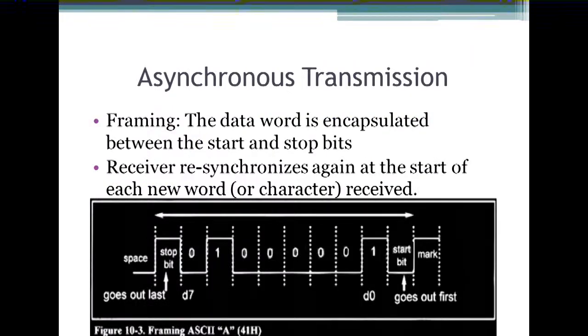Looking into UART, which is asynchronous: in asynchronous transmission, characters are transmitted one after the other, and they undergo framing, in which each character is added with some external bits, the start bit and the stop bits, which indicate the start and stop of characters, helping to synchronize the transmitter and receiver. After transmission of the start bit, the 8-bit character followed by an optional parity bit and a stop bit are shown. The entire collection of transmitted bits is called a frame.